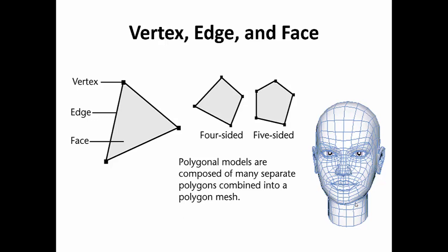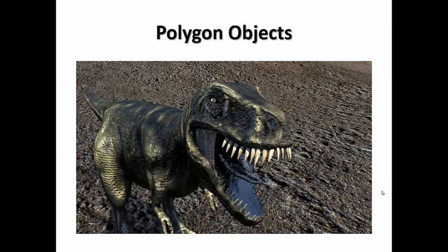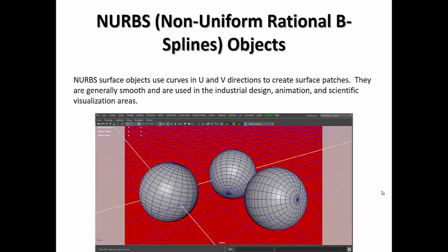They will basically pinch and distort any textures you apply to them, so n-gons typically are bad. You usually want to stick with 3 or 4-sided polygons, but they can combine into any kind of mesh. You can see here a face on the right that has lots of 4-sided polygons, and a few 3-sided ones in little corners, but typically you want 4-sided polygons. This T-Rex here is made up of polygons, and I created it.